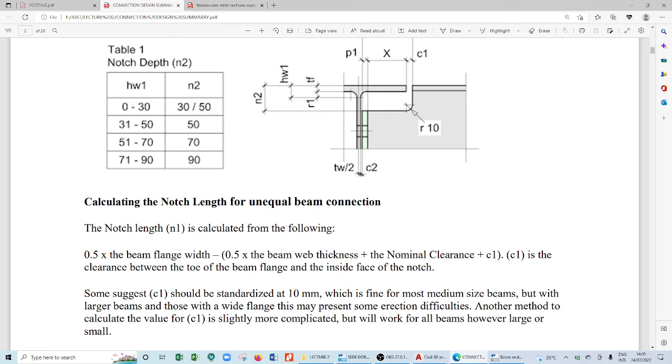So this is the flange thickness. This one is the flange thickness. This is called a web. In this particular case, it got 7.8. And the root radius is actually this distance. You don't want this to come and clash here. It will not sit properly. So you are trying to clear this curved section, because that's how I sections are made when they are rolled.